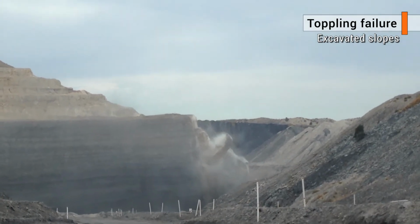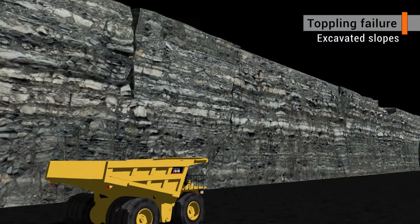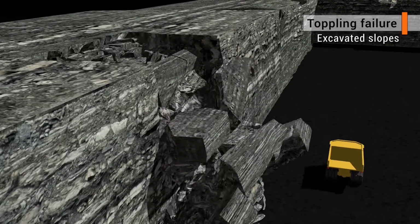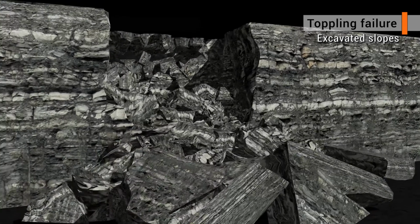Toppling failure. Toppling failure occurs when persistent defects dip steeply into the excavated slope and the blocks or columns formed topple out of the face. These failures generally have a weak layer at the base that the vertical blocks slide along.